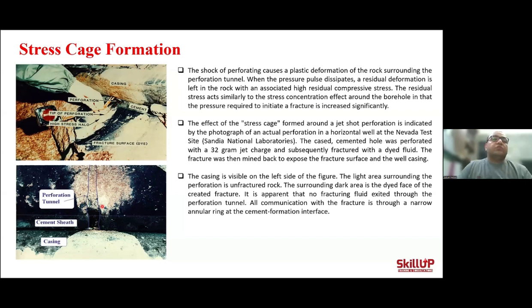Why? Because what do you need from the perforation? If you know that you will proceed with a hydraulic fracturing job, no one actually cares about the perforation length. We really care about the entrance hole diameter only, because the function of the perforation before a hydraulic fracturing job is just to pass the cement sheath and casing, and that's it, guys. So you really have to care about the entrance hole diameter only.